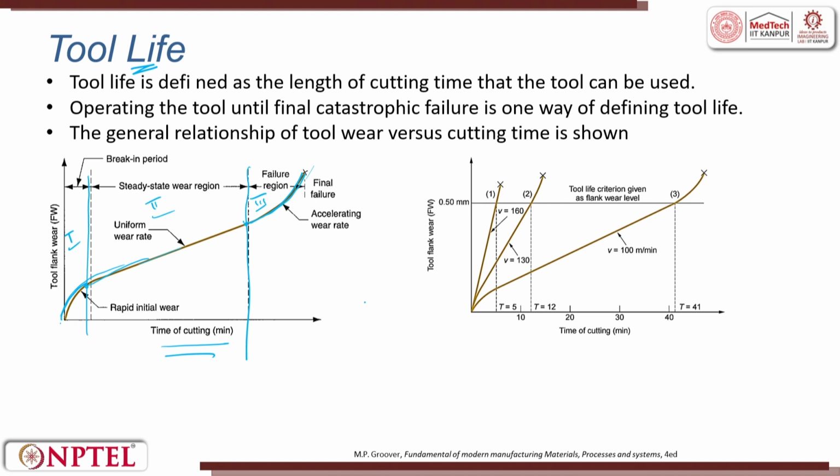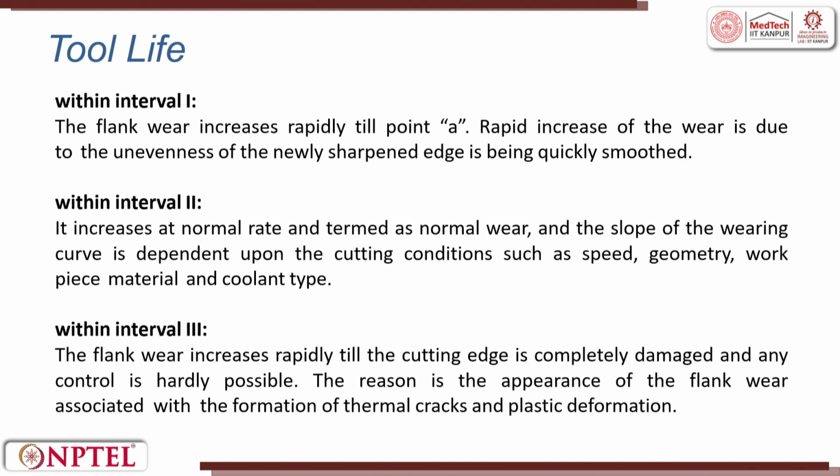So, this is the tool flank wear with respect to time. Here we try V equal to 100, at a cutting velocity of 100, how is this curve? 130, 180. When we go for a higher cutting speed, what happens? The tool life reduces. The temperature goes very high, all the wear phenomena happen. So, this tells us that as and when the velocity increases, the tool life decreases. Whatever I have discussed here, I have presented in this slide.